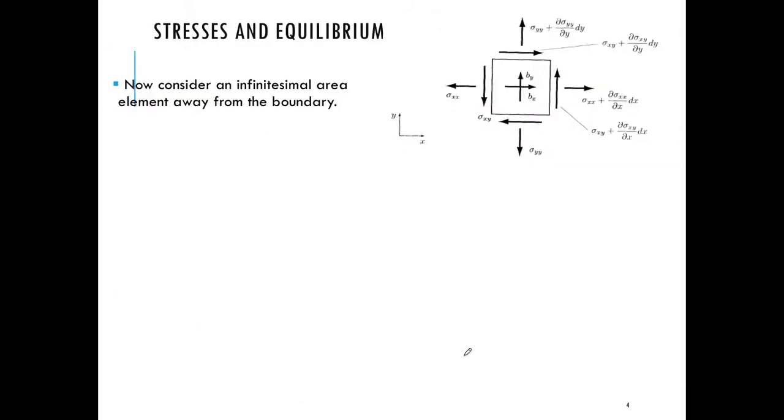Okay, so that's already started to lead us towards stresses, and now finally, of course, as we've been doing for uniaxial loading and for beam bending, we want to impose equilibrium within the body. So for that, I'm going to look at my stresses existing within an element in the main bulk of the body.